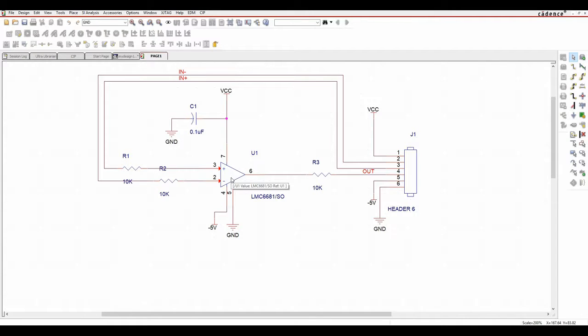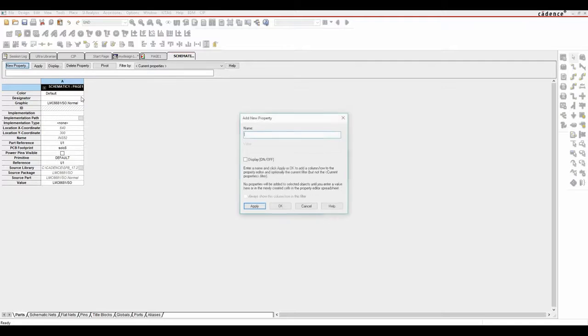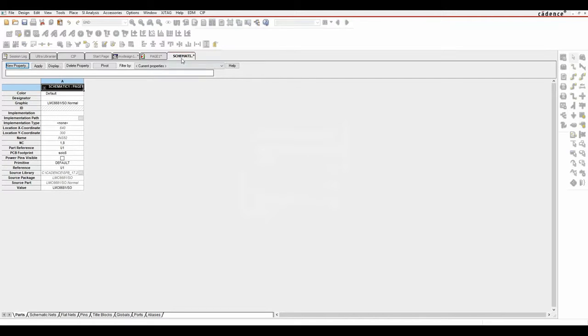So from a netlist point of view, we must make sure that we have the exact same number of pins in the schematic symbol that we have in the PCB footprint. So ideally we would redraw this schematic symbol so we have all 8 pins on it, and maybe show some NC pins, but in this example we can actually just add a property to this symbol. So if we double click the part, we can add a new property here. The property name is called NC, and then the value is the list of the pins that are not connected, basically, so it's going to be 1, 8. So it's a comma separated list. So if you had lots and lots of NC pins, you could put all the comma separated list in here to sort it out. So we'll click OK to that.